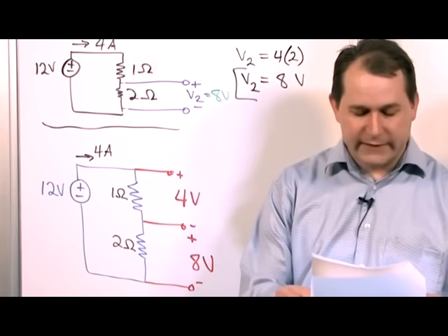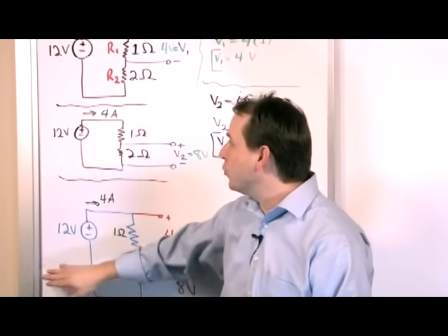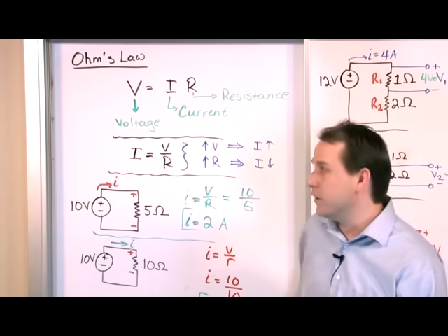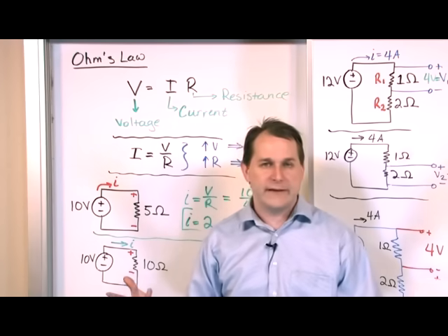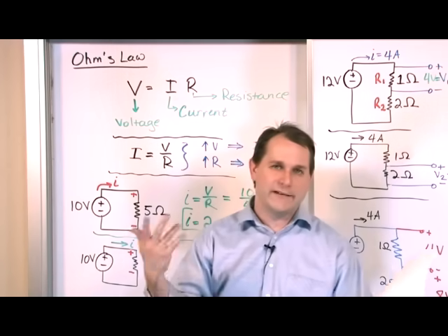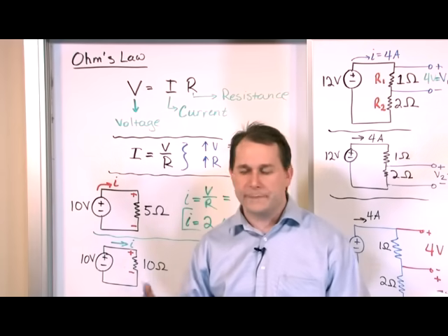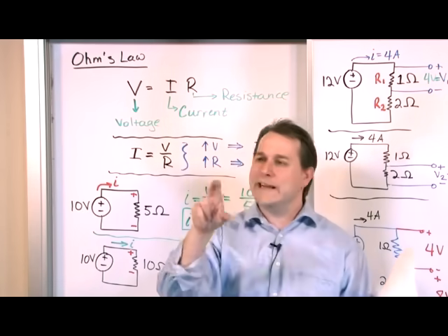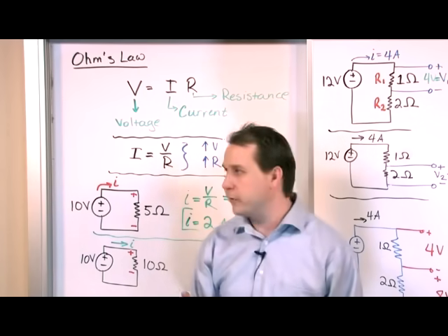All right, that is basically what I wanted to talk about in this section. It's one topic and one topic only, and it's so important that it deserves its own section. We call it Ohm's Law. Basically, it governs what we've talked about in words, that if you have the push, which is the voltage, and your resistance, which is in the way, so to speak, then if you know those 2 values, you can calculate the current flowing in a circuit. Ohm's Law applies to the whole circuit, but it also applies to the individual elements that the electricity is flowing through in a circuit.